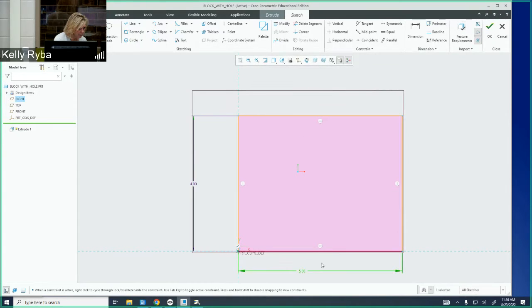If I go down here and I click off of it, now, when you have it activated, notice that 5 is green, but when I release it and re-click somewhere else, it becomes black. Now, when these dimensions are black, that means that I'm fully constrained, or in SolidWorks, we would say fully defined, right? We didn't leave our sketch until everything was black, and I think the outline was black too, right? But our outline isn't black, but that's okay. But when you get, for instance, this okay over here, that means you can save, you can be done with your sketch and move on.